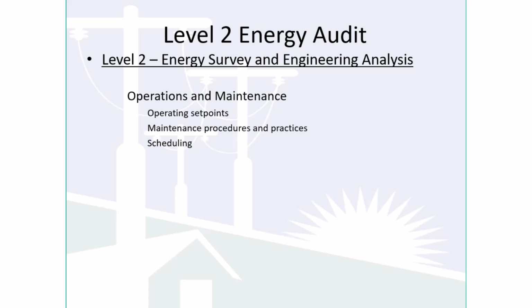It's also to review how the facility is operated and maintained. By operating, we want to know what the set points are for the heating, the cooling, the chilled water set point, the heating hot water set point. All those set points: where is the facility's equipment being set to try to maintain?